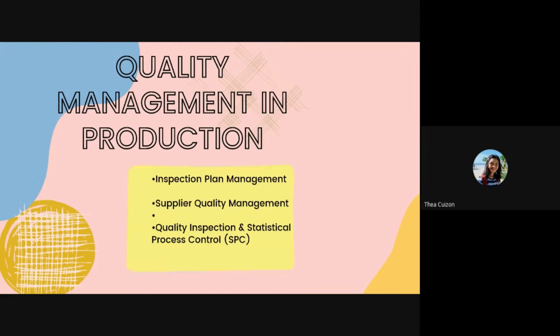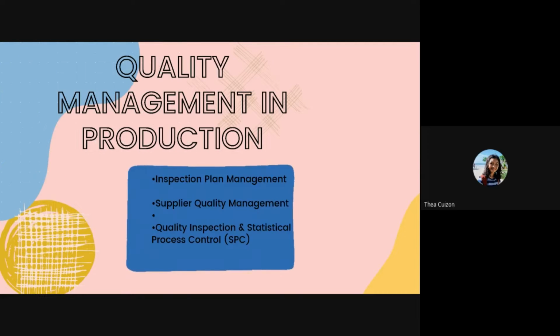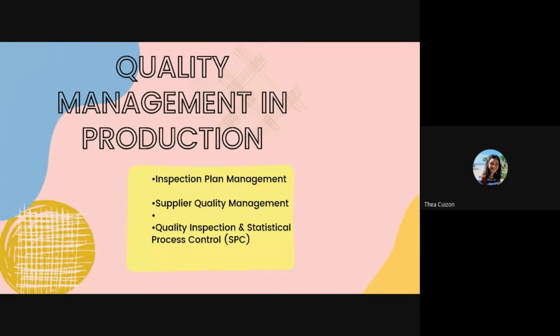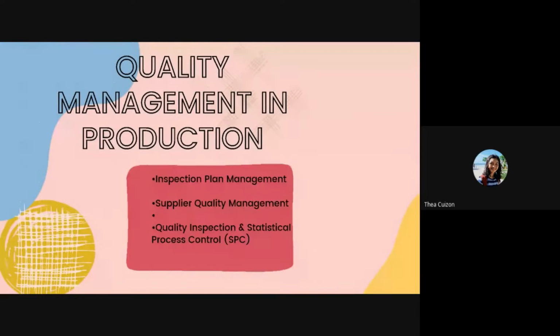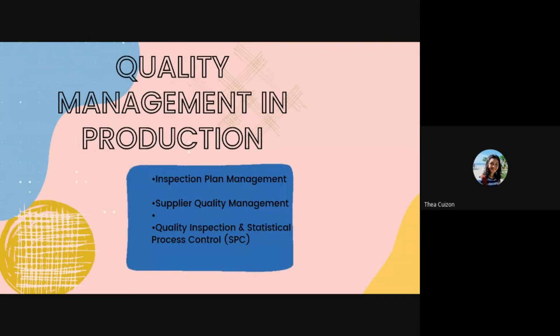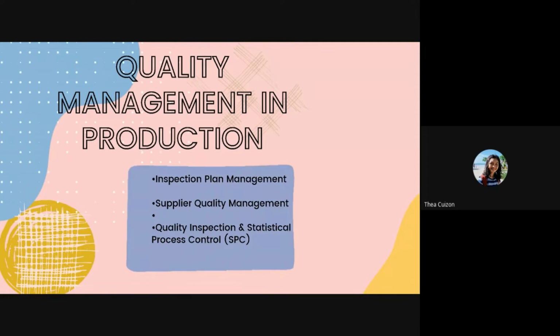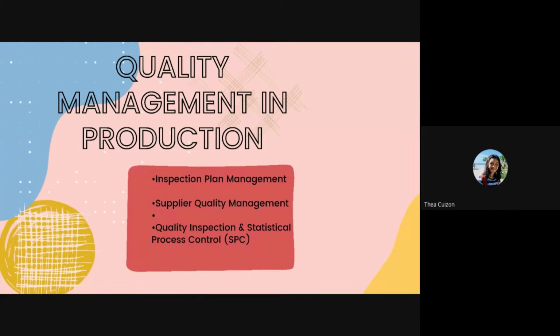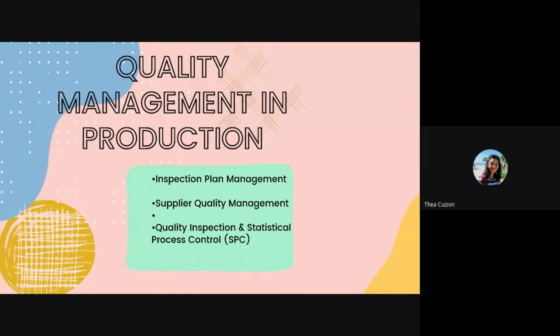It's a methodology for measuring and controlling quality across the life cycle. It contains tools to aid in the detection of tolerance variation, the identification of root causes, and the correction of faults. Users generate control charts in a typical SPC process to graphically visualize and differentiate between coincidental and systematic quality variations that influence the production.